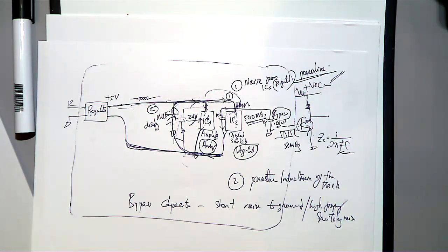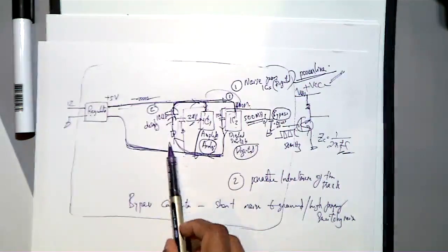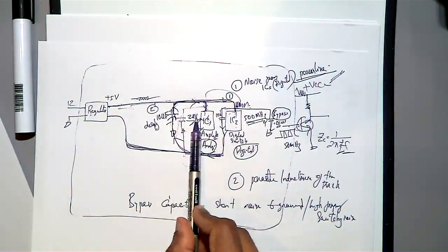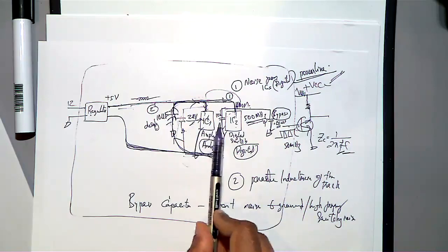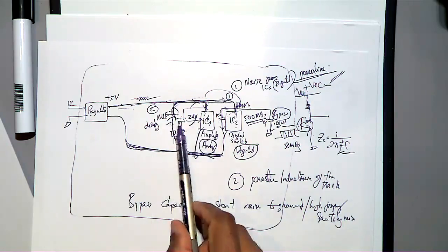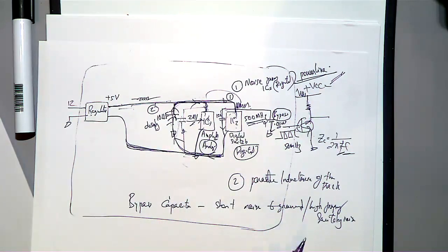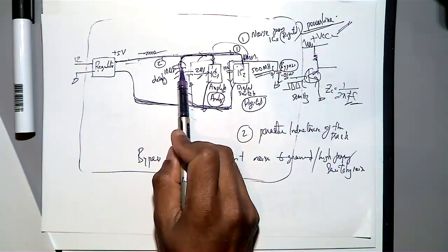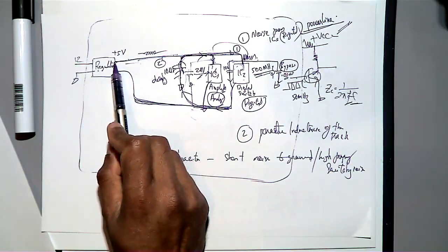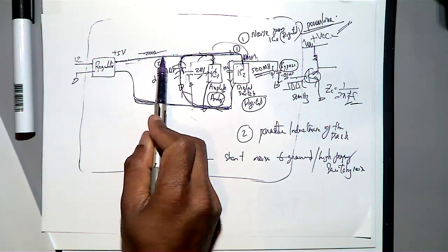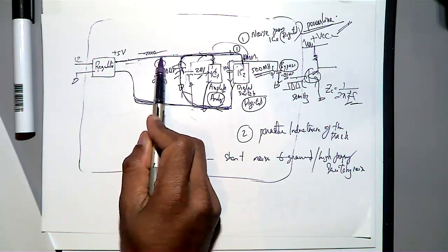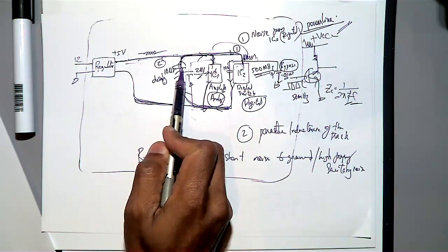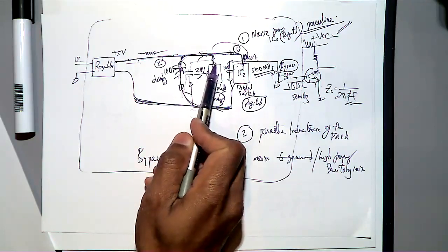Because of the size problem, because this capacitor is so big, we connect like this, and then the bypass will work out. So with this we solve the issue. Even this is much better than drawing directly from here. Not only because of the track inductance, but this capacitor will also make your circuit very stable.